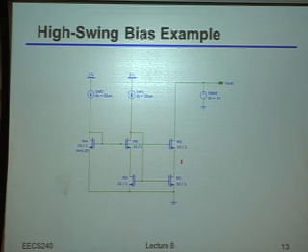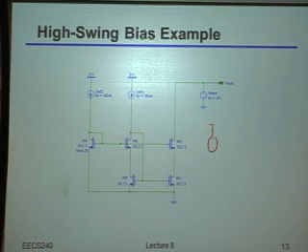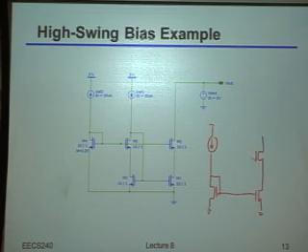Now, that's actually not, I think, too particularly interesting. What I did want to ask, however, is there's kind of an interesting, and perhaps somewhat important point as to how exactly I set up this circuit here to even do the current mirroring function. So in particular, I want to contrast what's drawn here against what I might have tried to do in a naive way, which would have been something like the following. If I wanted to do the current mirror, I could have just done something that, at least structurally, would look like this.